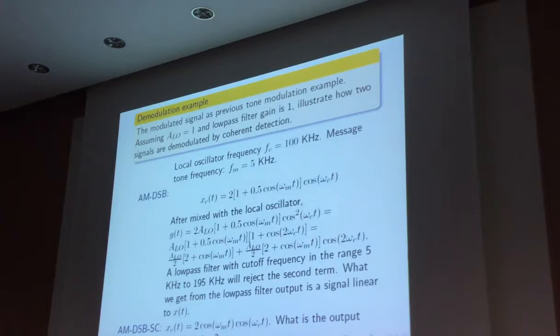I haven't talked about unsynchronization of the frequency yet. I'm talking about phase difference. I haven't talked about frequency difference yet. Right? So if this is like this one, what's going to happen? This term multiplied with this one is a high frequency component, so we can remove it. But the recovered signal is going to be cosine omega_m t multiplied with this cosine theta now. Right? And consider that this theta generally can be a random variable. That means it will change from time to time.